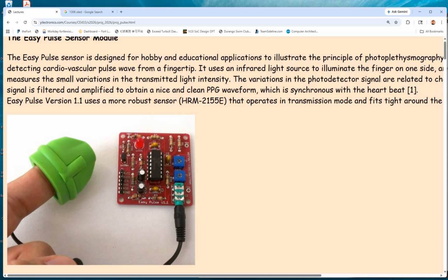Just to let you guys know, for the modern cores, even for 180 nanometers, I think we do the same thing, let alone the lower voltage, lower technologies. So 3.3 volts could be a power supply of the chip, but whenever the voltage is delivered to the core, the core is running at 1 volt. That's very common for modern technologies, especially for 28 nanometers. For lower, probably 1 volt as well. So the thing is, why is 3.3 volts still needed?